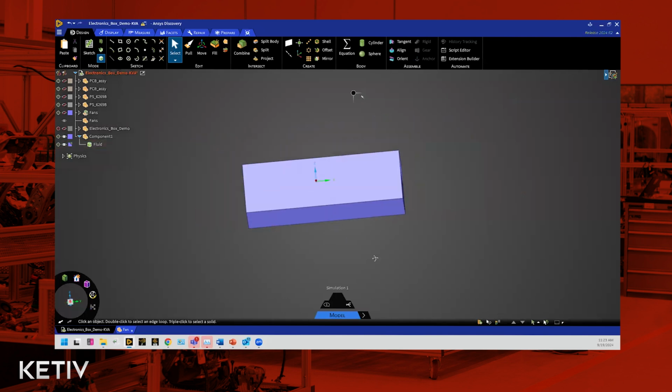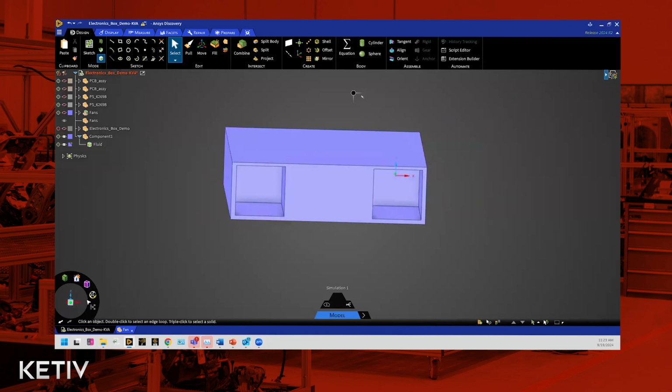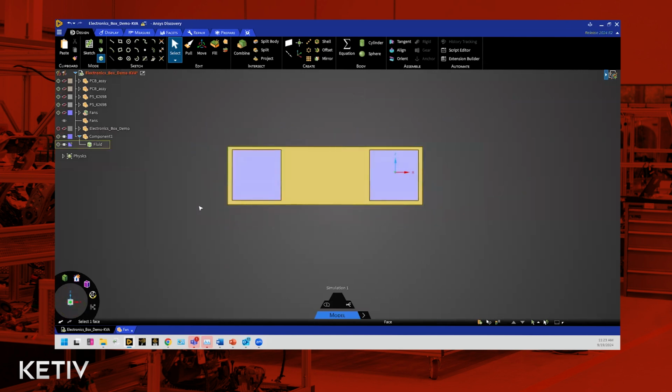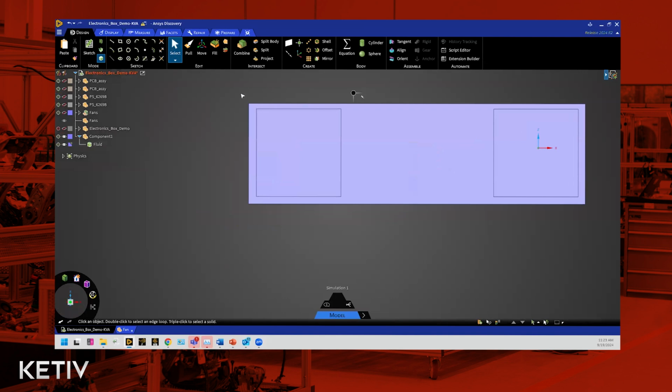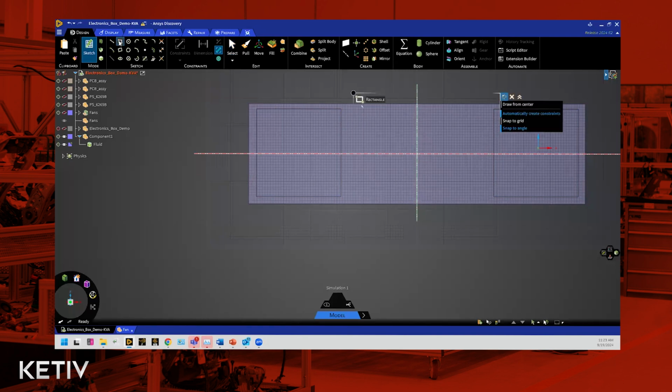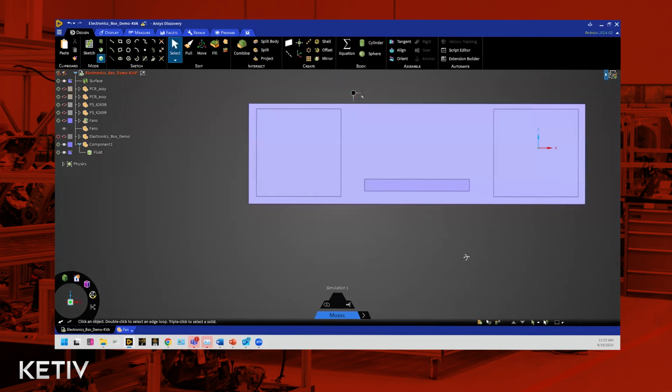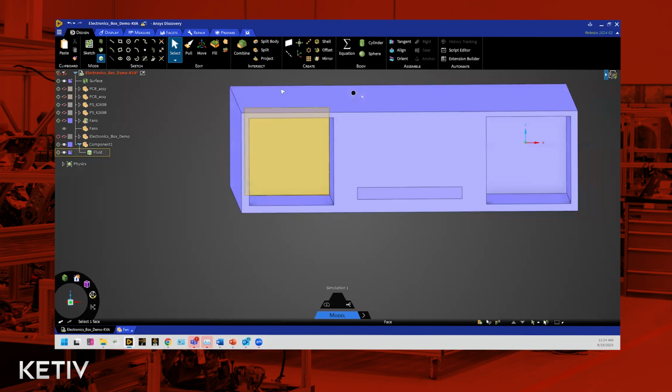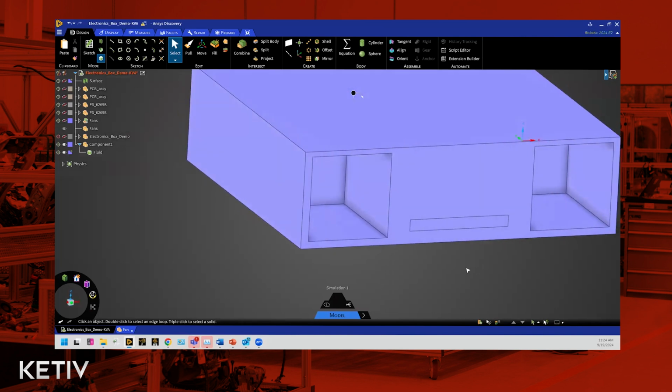Let's also go ahead and create an outlet. I'm just creating an arbitrary outlet. It could be a grill, it could be some other type of geometry, but this is just to show you guys. I'm just going to create a random opening over here. This is a surface in the structure tree. Let's just go ahead and project it, and you should see that outline on your original domain, okay?